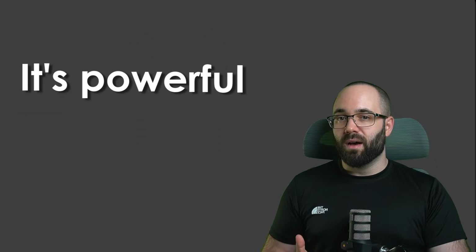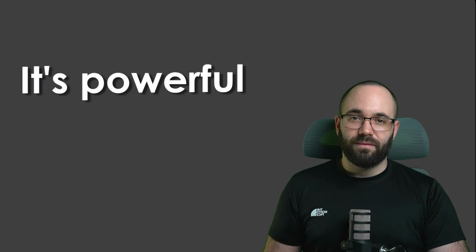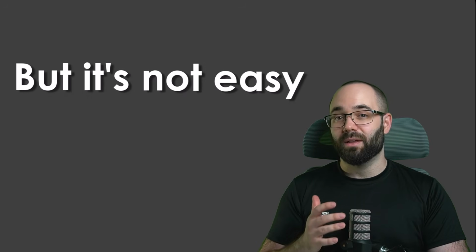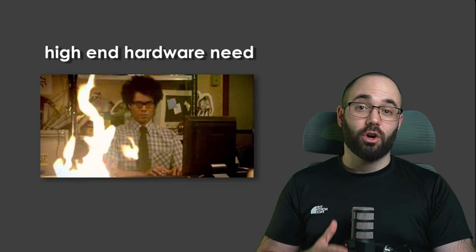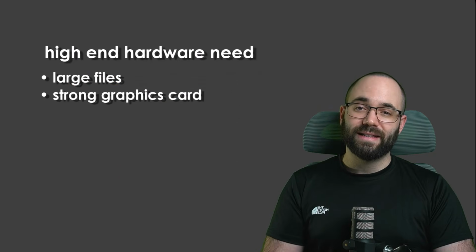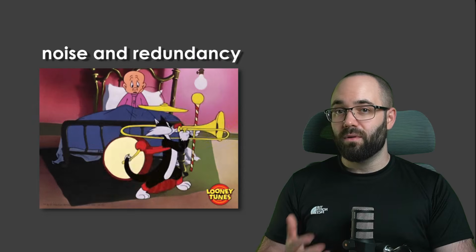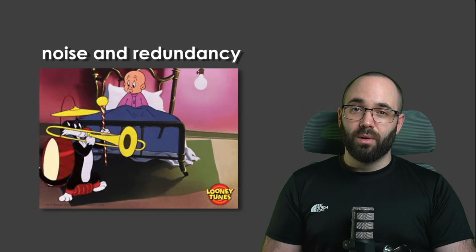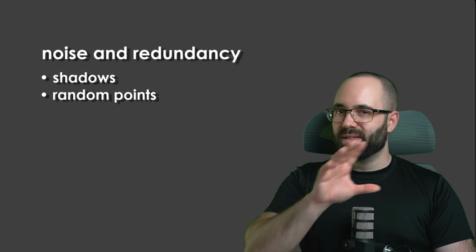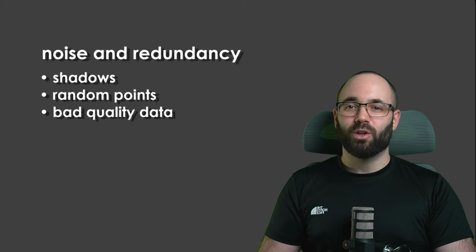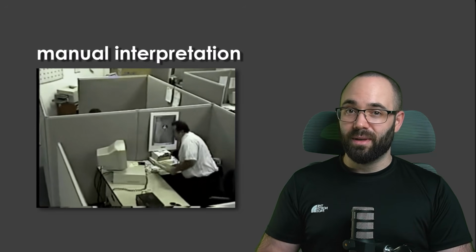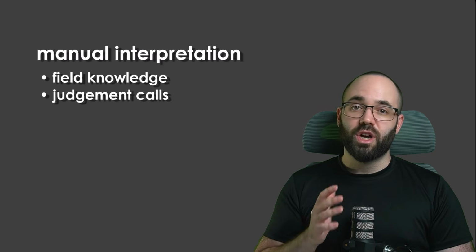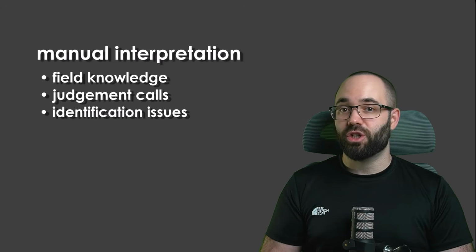This whole process of scan to BIM is powerful and efficient, but also has a lot of challenges. First, we have high-end hardware needs. Files are large and we need good graphics and a lot of RAM. Then we have noise and redundancy with things like shadows, random points kind of flying around the place, and bad quality data. Manual interpretation is next, with need of field knowledge, judgment calls, and identification issues.